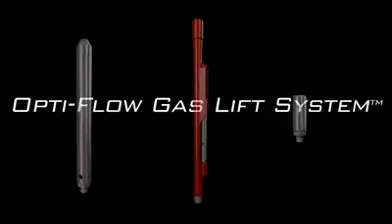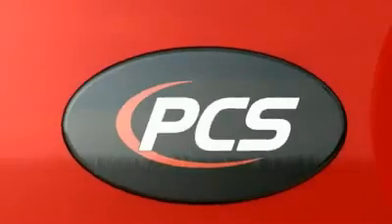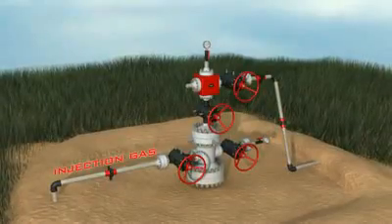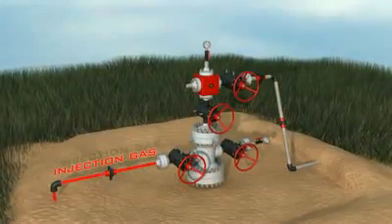The OptiFlow gas lift system, by PCS, uses a high-pressure source at the surface to inject gas down the annulus into the tubing. The compressed gas is injected into the production stream through gas lift valves fitted in integral mandrels. The mandrels are installed as part of the tubing string and are positioned at prescribed depths.